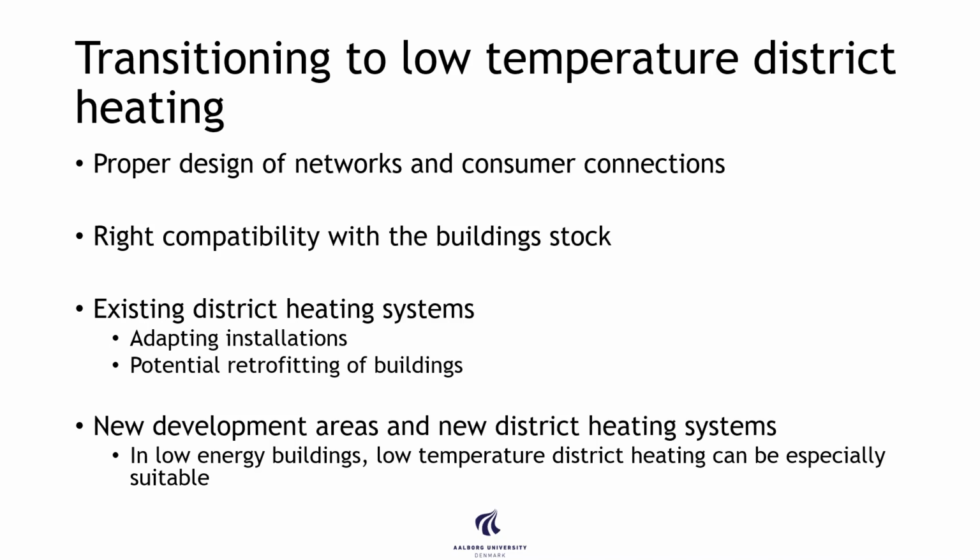Because we are lowering the supply temperature as much as we can, the difference between the supply and return temperature changes. So the delta T between those two will become smaller potentially, because there's a lower limit to how much we can cool the water. So it is very important to focus not only on supplying water but also on cooling the water.